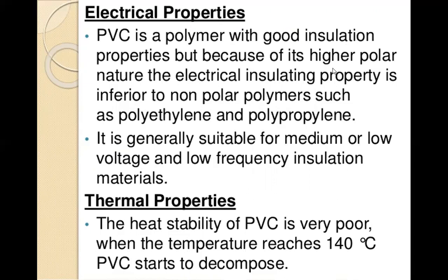But because of its higher polar nature, the electrical insulating property is inferior to the non-polar polymers such as polyethylene and polypropylene. And coming to another electrical property, it is generally suitable for medium or low voltage and low frequency insulation material. Coming to the thermal property,